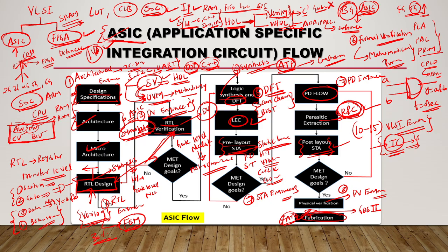Why we are using design verification means up to FSMs you can verify with Verilog. You can write the code and test bench. Suppose complex IPs are there, complex SoCs are there, like an i5 processor or Ryzen 7 processors and system on chip, suppose Raspberry Pi, and so many complex IPs are there. Those IPs we can't verify with Verilog. So we need to go for these UVM related methodologies. Parallelly with mathematical formulas, you need to verify that this is matching your specification. That is nothing but formal verification.